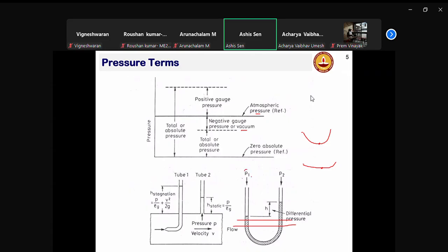You start from this pressure, go by all these stacked layers to this level. Hydrostatic pressure is rho1 g h1. Here also you go from atmospheric pressure to that level. And you fix your reference point. It could be the bottom of the meniscus on both sides, irrespective of whether this curvature is flat or more U-shaped. But be consistent: whatever reference point you use on the left, the same reference point should be used on the right hand side. Okay, understood.